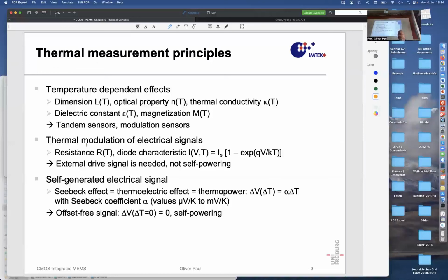So this is what happens very often. And of course, in particular, thermal devices are also temperature dependent. And we appreciate them strongly because we know how to build them into systems in order to get some signal out. It's not a complicated optomechano whatever setup that ultimately provides the temperature changes. It's maybe just a resistance measurement, a very easy thing to do. You need a current source and a voltage measurement instrumentation in order to determine a resistance. And if you would like to implement a bridge, then it's even easier.